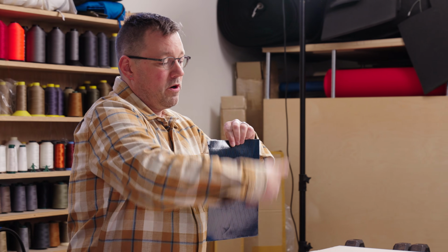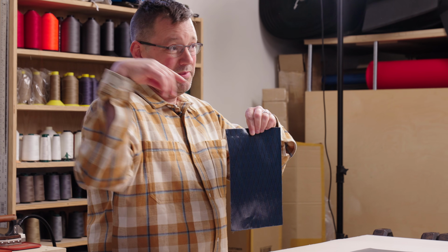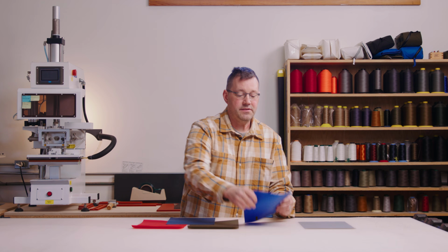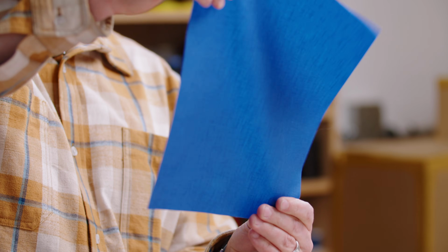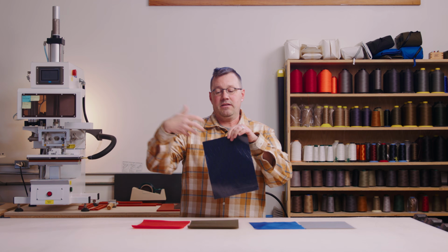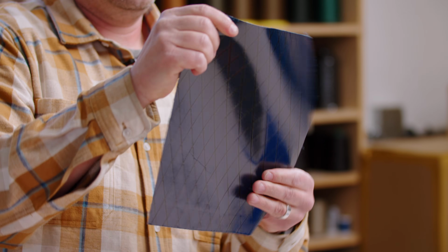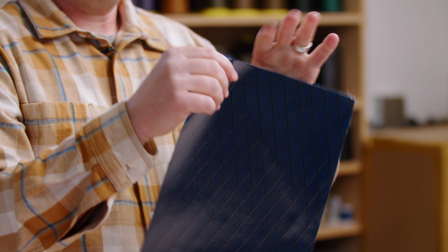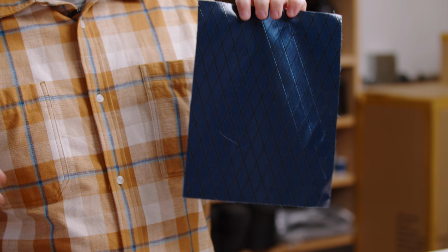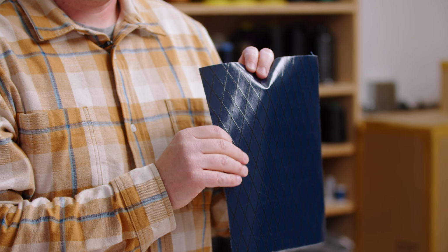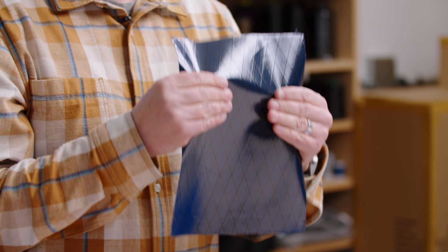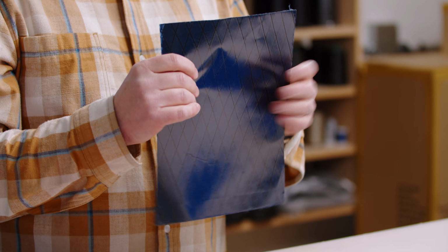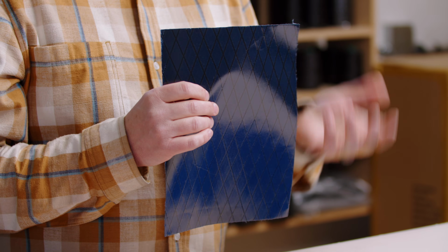So I talked about warp and weft. Bias would be diagonal. Most textiles are very stable if you pull straight on the yarn. If you pull them diagonally, they'll flex a little bit and stretch a little bit. So this X-Ply is laid in here to stabilize this against stretching in the diagonal direction. Then to put the package all together, it has a lamination of Mylar. This is a monolithic Mylar film that's laid on. All the components are bonded together. So that makes this textile waterproof and air impermeable.